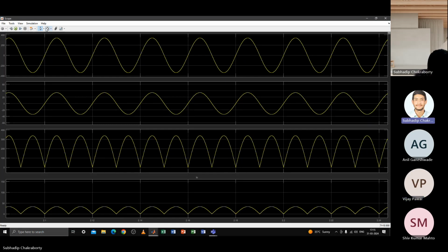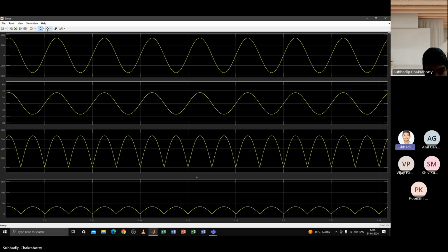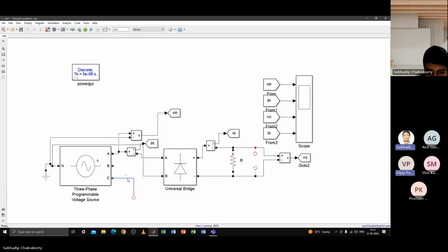Please understand. If there is phase shift in the waveforms, if you decompose them into their fundamental components, there will be some phase lag or phase shift, right? So cos of that phase shift will give you the active component, and sine of that phase shift will give you the reactive component. Then also the power factor is not unity. But power factor can also be non-unity during the existence of distortion in the waveforms. Do you understand that? Let me show you one simulation, you will understand. It is possible that power factor is non-unity even if the waveforms are completely aligned.